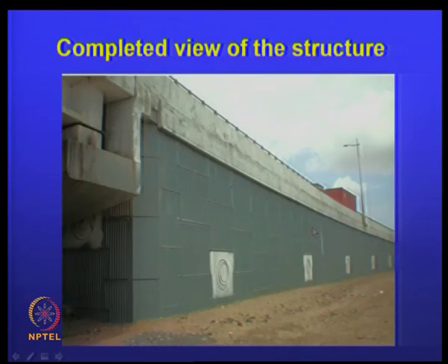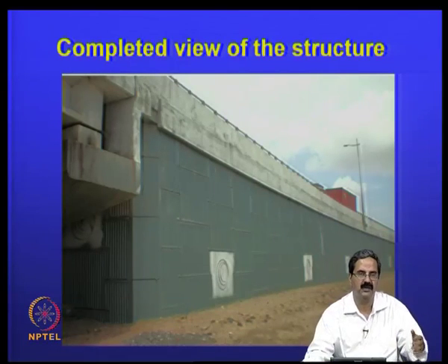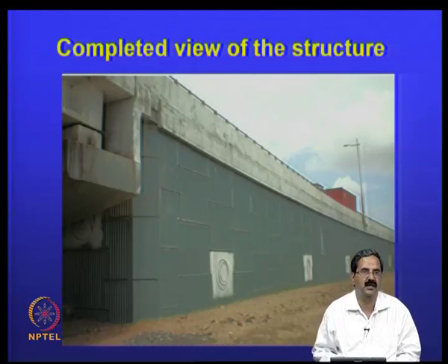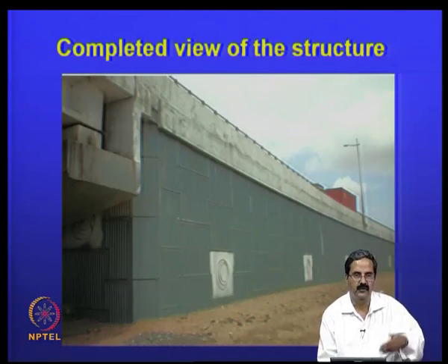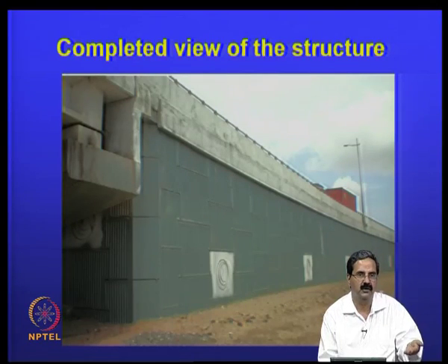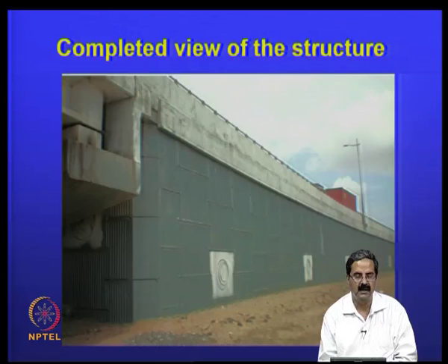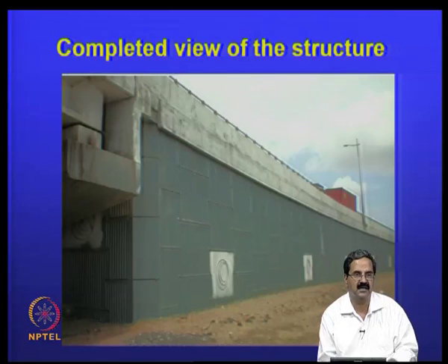Actually, there are some cases where voids are formed in the ground. I was just mentioning one case where voids may form in certain deposits, and you do not want the loads to be transferred to them, because it is very difficult to fill up the void. We do not know where the void starts and where it ends. One conventional way of filling up voids is to use a lot of cement grout, and yes, it can be done, but at the same time, if you want to ensure that no loads or stresses reach that,